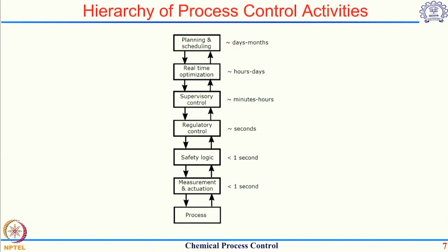For example, in the example of the steam pressure cooker which I showed you, the pressure cooker also comes with a safety valve. If there is some problem with the whistle, and it gets blocked and does not open or close, there is always a rupture disc on top of the cooker, which will open if the pressure reaches some unsafe limit. As soon as that happens, irrespective of whether the whistle is working or not, the burst disc will burst and the pressure will be released.